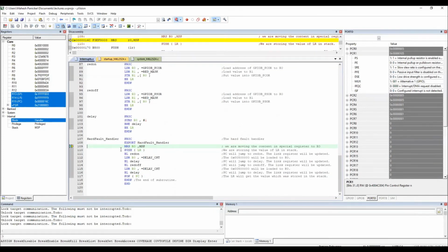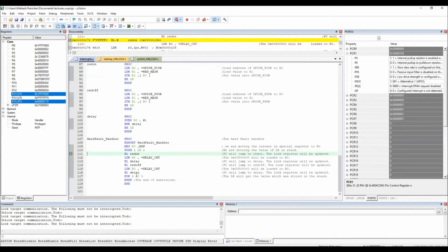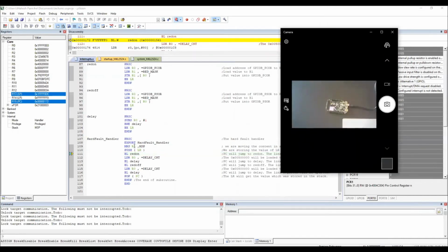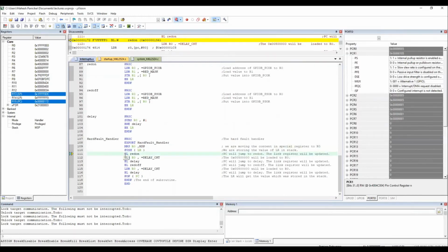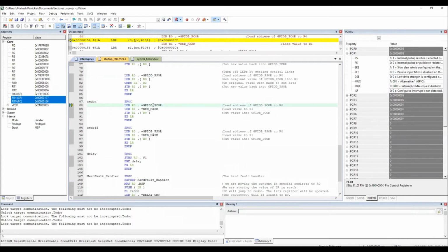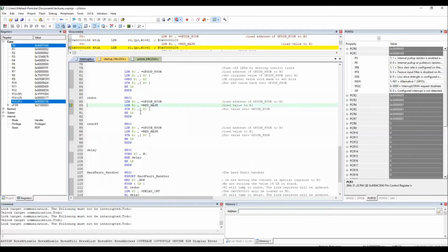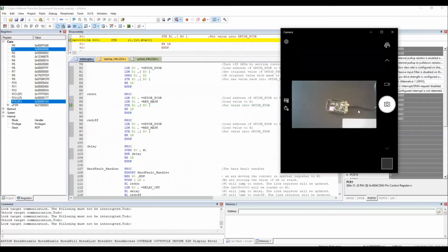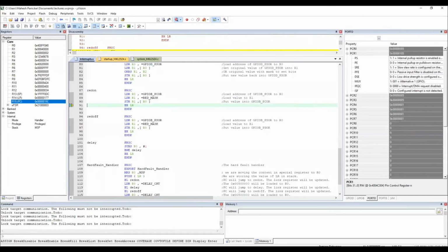Now I'm here. So as I said, I'm pushing something to stack just to ensure that when I return at the last stage, I can return back to the main program from where I came, right? So now just check here. This is already blank, okay? Now if I make this LED on, which is actually the entire function, which is here. So corresponding register, I'm going to clear it, okay? Earlier we were setting it PSOR, now PCOR. So if I do it, the moment still it is off. The moment I do this, you can see the LED is on. So I turned on the LED.